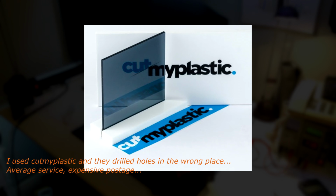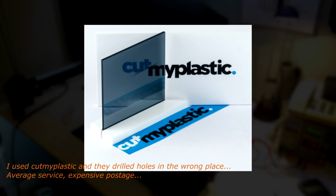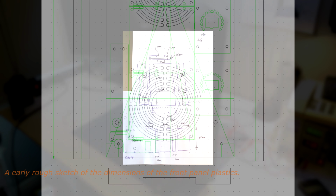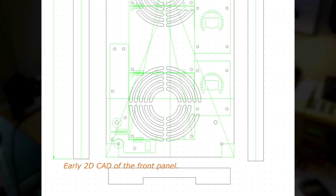Part 4. Final assembly. The casing itself is made out of black 5mm acrylic. The front panel is made out of 5mm clear acrylic with a black tint. This was chosen so when all the LEDs are off, it all looks black. I designed the panel in 2D CAD. I went to a local hackerspace with a laser cutter to cut the acrylic.